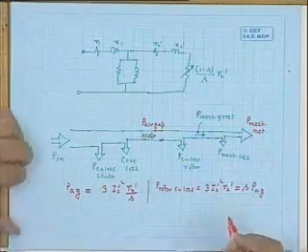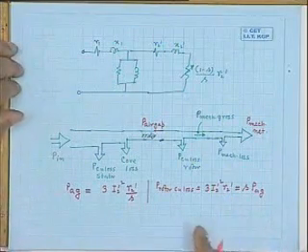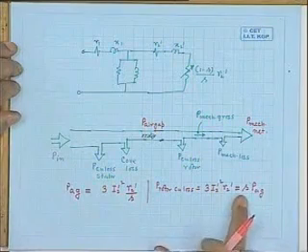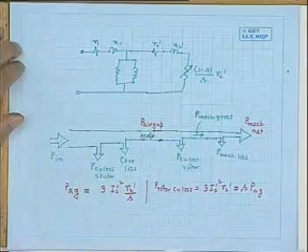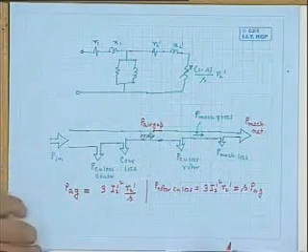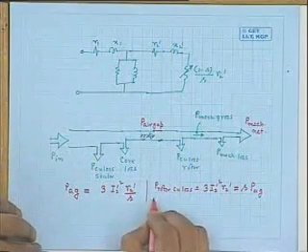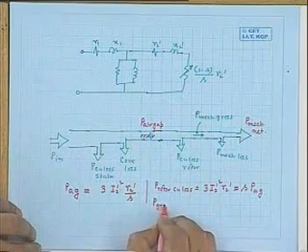So you see this happens to be equal to S into PAG. These are very useful relationships while solving problems. See, air gap power multiplied by the slip at which the machine is operating gives you the total rotor copper loss.